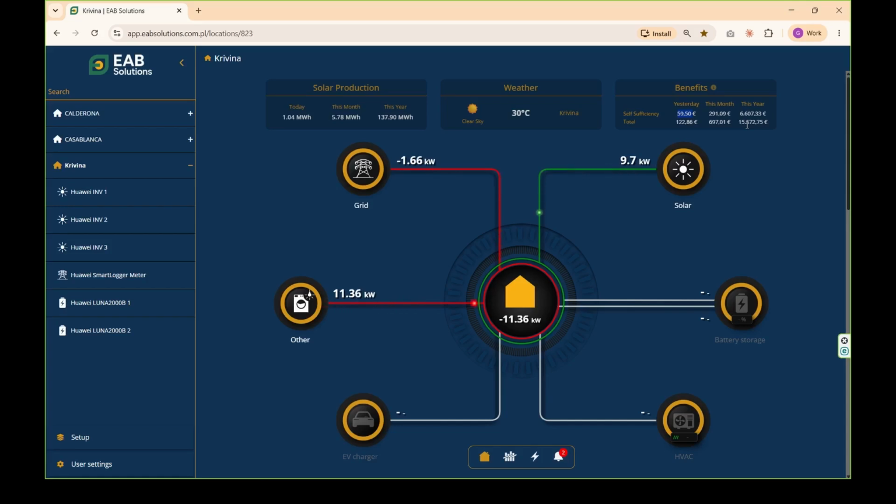A market that needed it, that had heard about batteries, where there's interest in batteries, but in the end, a PV installation at a client's site with batteries simply bolted on, and a dumb EMS doesn't produce these kinds of results. It produces mediocre results, because the EMS in those cases only charges from the solar surplus, and the solar surplus usually isn't much, so there's no substantial extra return. The substantial extra return comes from arbitrage done well, and that's where we, with our EAB system, tend to shine.